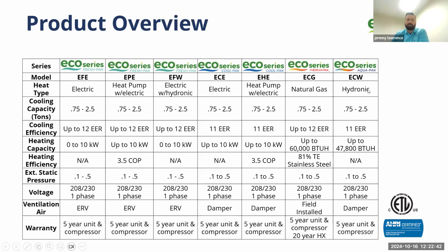This ECW in Ontario, ECWs have been the primary PTAC unit that we've done for 30 years. We are certainly seeing more of the heat pump versions coming in, but typically if they're going to move from hydronic to heat pump, they're going to add that fresh air ERV in it as well.